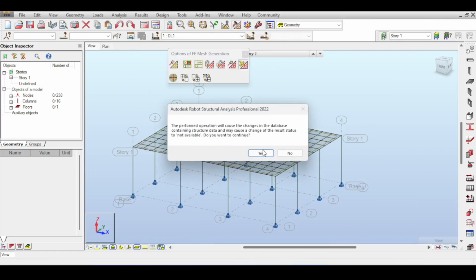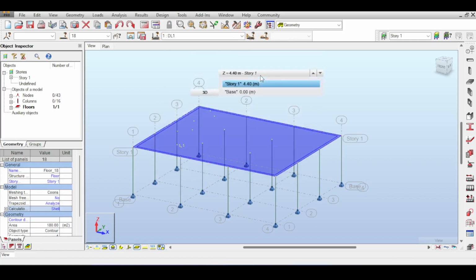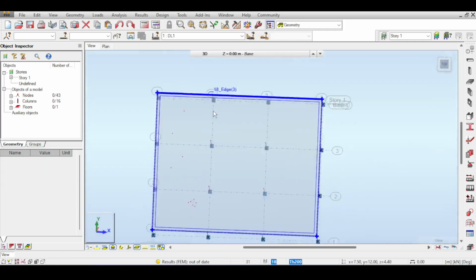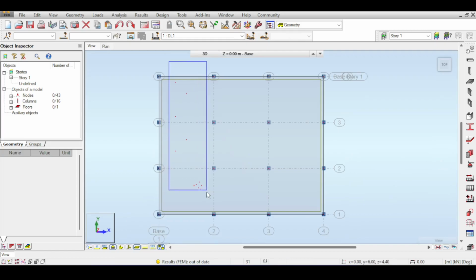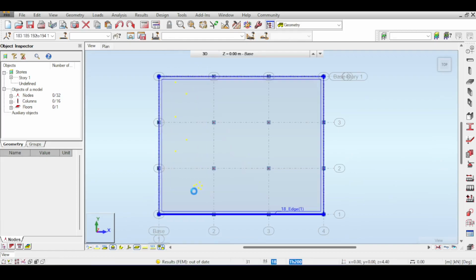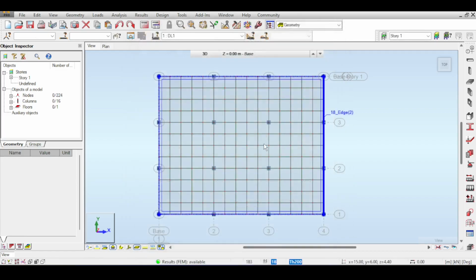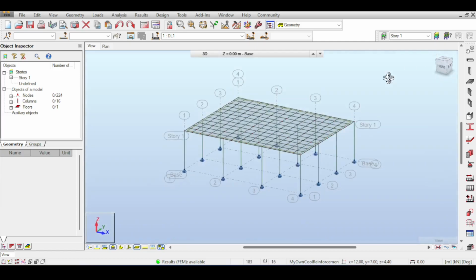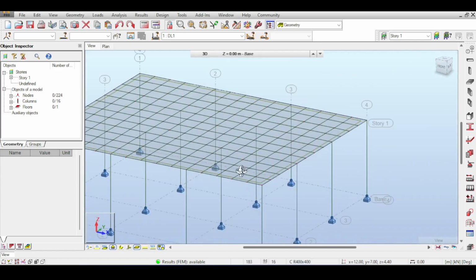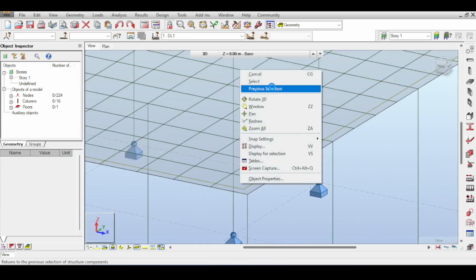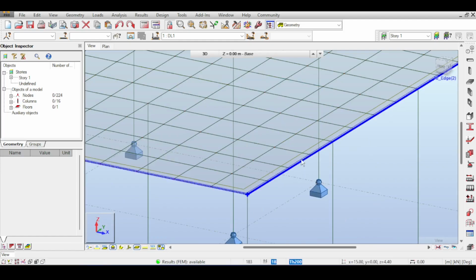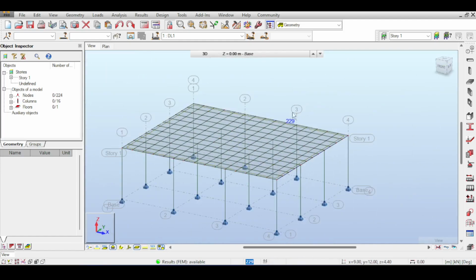Now, me being a programmer, I've been personally dealing with mesh generation, and I tell you, it is not a joke. By the way, I deleted those extra points I added because I want to go back to my normal mesh. What I mean by this is that when you mesh, this beam needs to be cut into pieces. Any beam that passes through this slab must be connected to the slabs at the nodes.